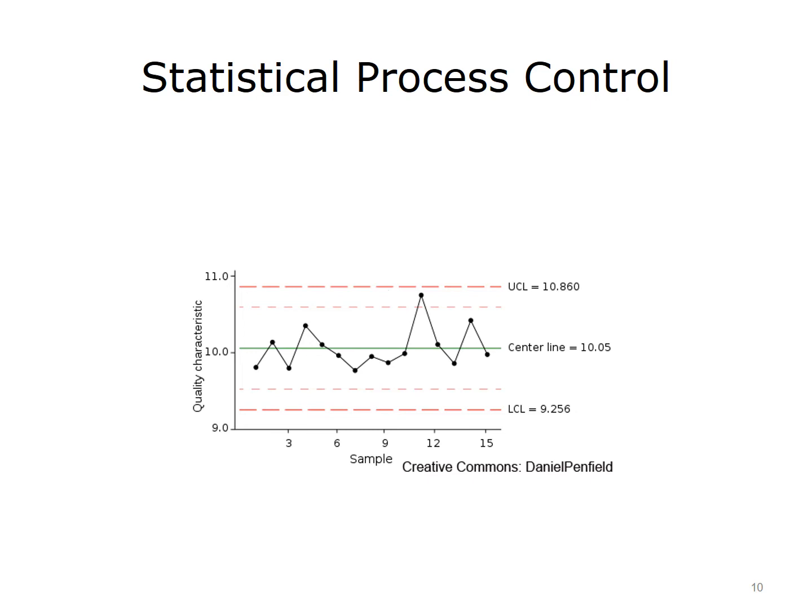If analysis of the control chart indicates that the process is currently under control, that is, stable, with variation only coming from sources common to the process, then data from the process can be used to predict the future performance of the process. If the chart indicates that the process being monitored is not in control, analysis of the chart can help determine the sources of variation, which can then be eliminated to bring the process back into control. Control charts can be used to determine the process's stability regarding variation. If the process is stable, you can use that information to forecast the success of the operation. If the process is not stable, you can assess the chart to pinpoint and then attack the reasons for the unpredictability.